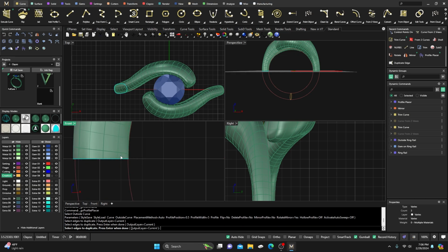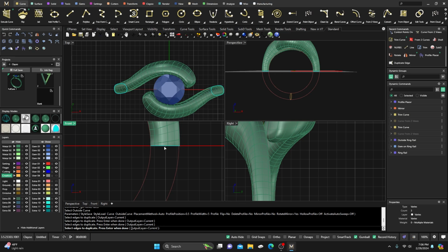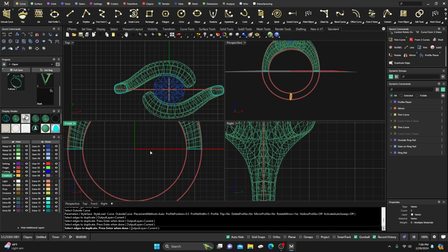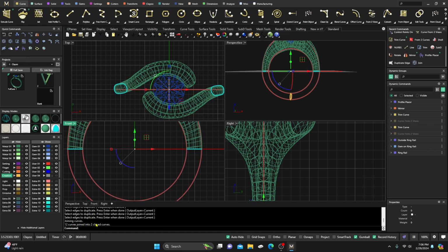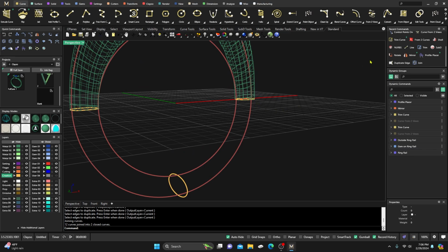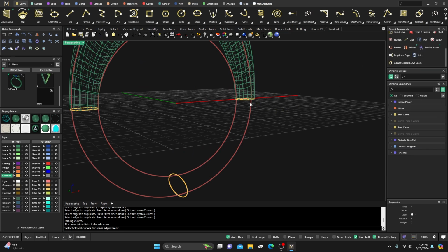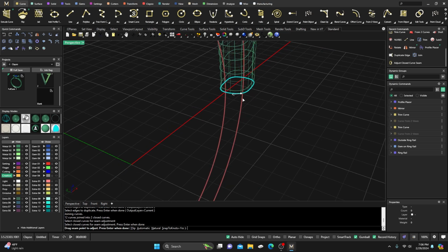There's one back here we don't want, and we'll just select these here by holding down shift, and that looks okay. Yeah, those are okay. We'll hit enter, and then we will join those together, and we will check to make sure that they're two closed curves. The next thing we did, since we selected those curves and did a dupe, you want to go in and check edit tools, adjust close curve seam, and make sure that they are going to be lining up.